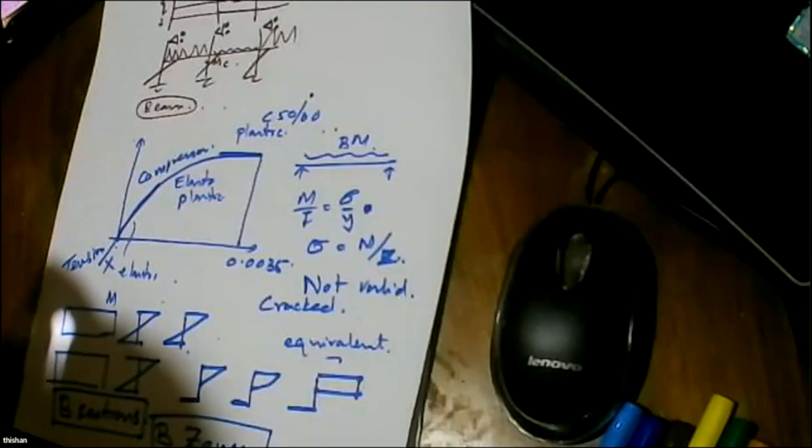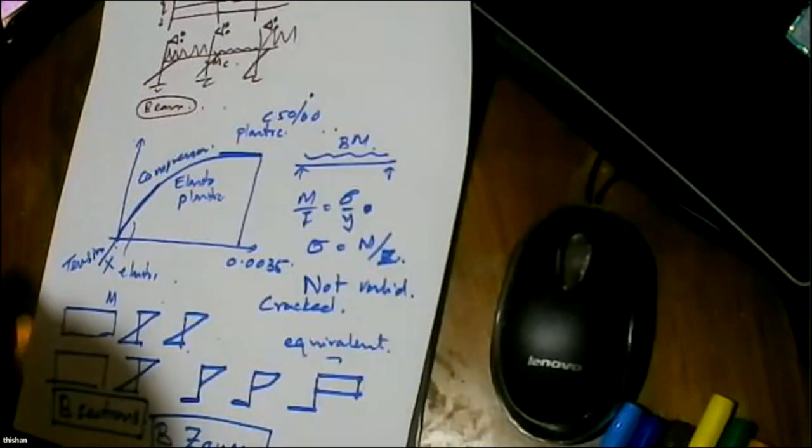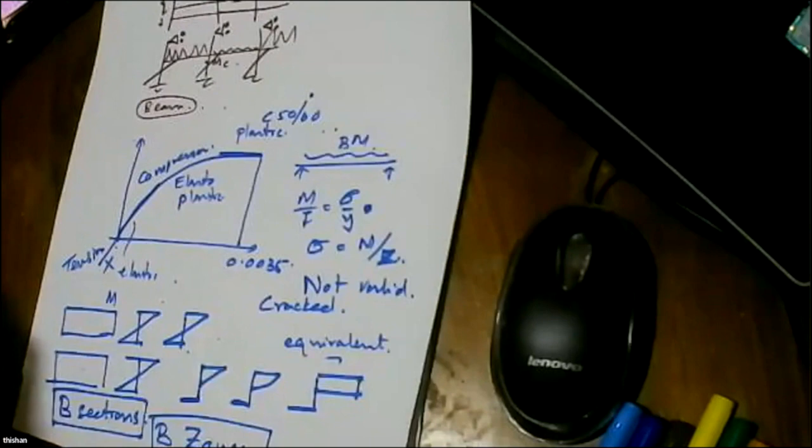Even the structural engineer inquired, and the geotechnical engineer said, no, unfortunately I can't give more because the ultimate compressive strength is low. So we found that we are dealing with a 30-story building and we would have to spend a lot of money on the pile foundation. Then we started looking at it. We investigated again why the geotechnical engineer had given such a low capacity for N bearing. Then we found the geotechnical engineer was correct. There's a big problem in that particular site.